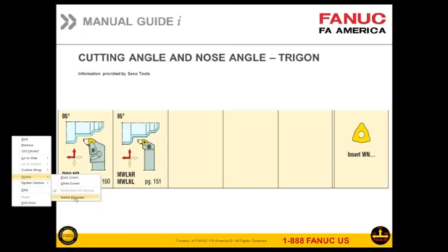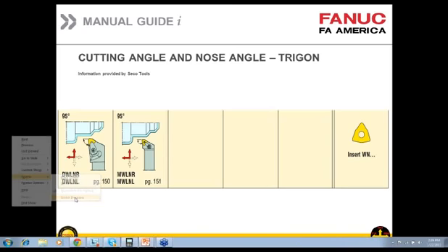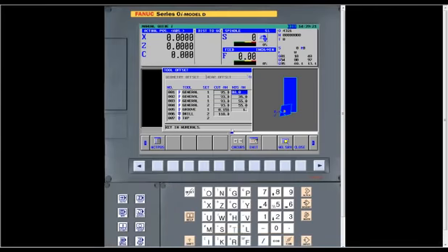Now at this point, we'll go back to NC Guide. So that's the type of information on these first 4. I've got turning tools, so 35 degree with a 93 degree cut angle, and 93 degrees with a 55. Those are all my turning tools. Basically a rough, a finish, and a semi. So those tools you ought to be able to get into almost anything.